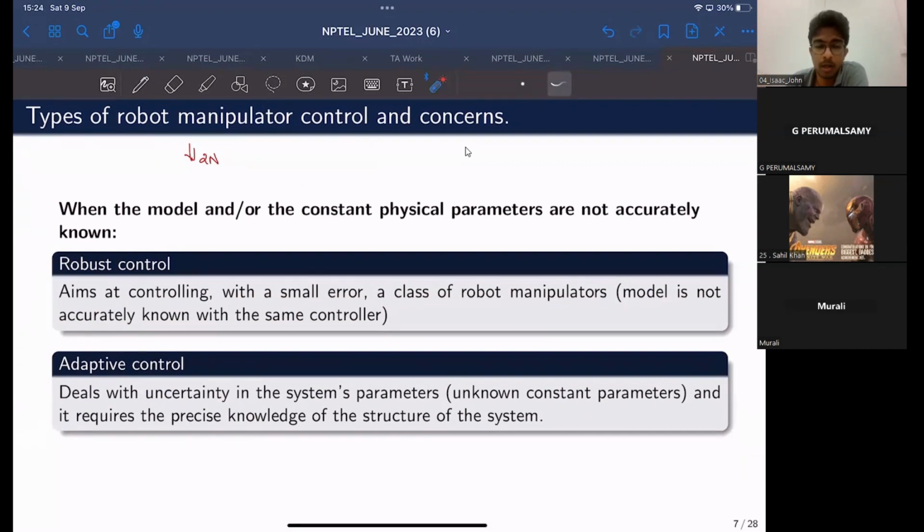It's due to something that is out of our hand. While designing the controller, we can design in such a way that a large amount of force is always going to be acting on the robotic manipulator, maybe the likes of 100 newtons or something. So we can model something based on a threshold, a higher threshold, right? The reasoning behind this assumption is that no matter what happens, this external disturbance is never going to exceed what we are actually modeling it for.